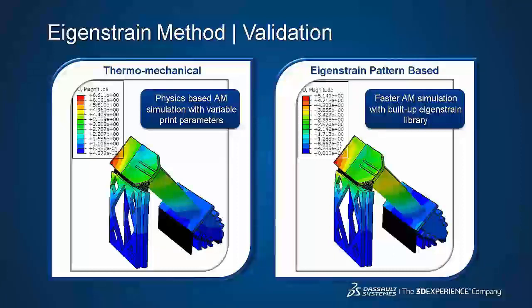The thermomechanical approach, on the other hand, shows high value in prediction of higher order structural deformations during the print, such as buckling, and capture of the microstructure phase transformation and resulting final material behavior.